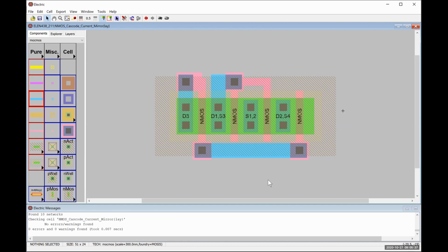Even the doped polysilicon has a resistance of something around 100 ohms per square, whereas the metal has something around less than 1 ohm per square. And so if I want to make sure that these gates are at the same potential, I need to make sure that the resistance, there's not going to be an appreciable voltage drop over that. There shouldn't be any gate current flowing or anything like that to cause a drop, but I'm just trying to play it safe here.